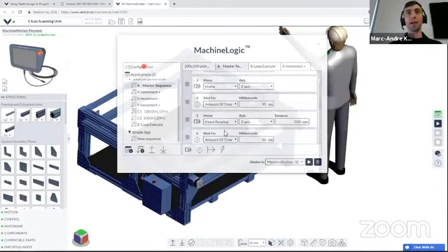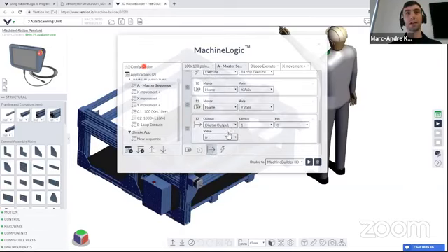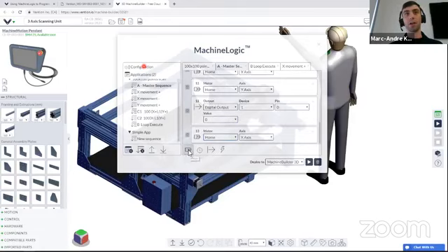You will need to add, for example, in my master sequence, an activate device block here. From a digital output, making sure that it's the right device and the right value to say activate or shut off. From this point, you can add a move. So add the motor and change it from home to move absolute or move relative.